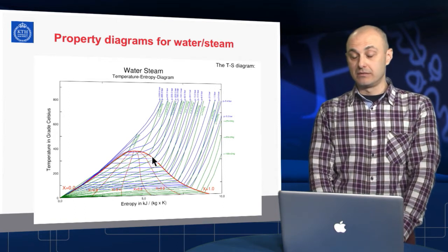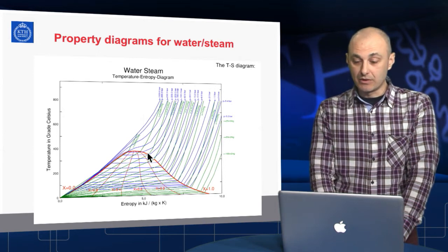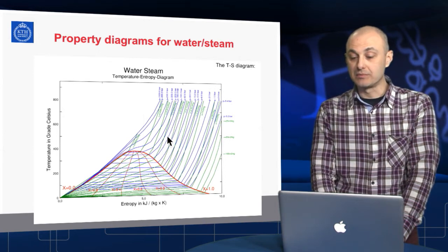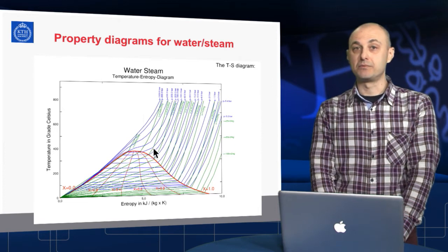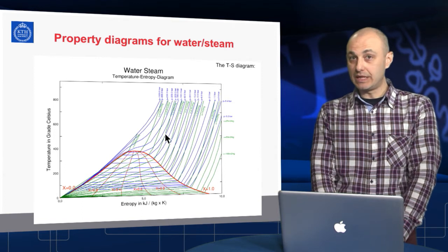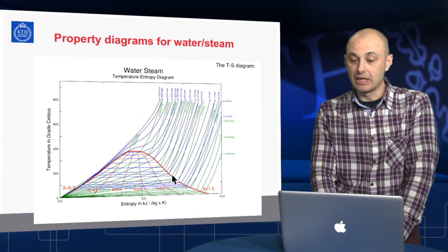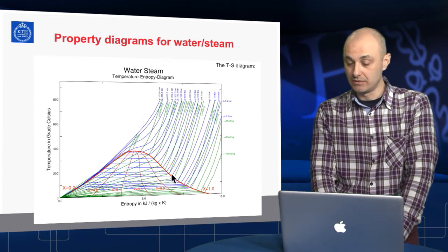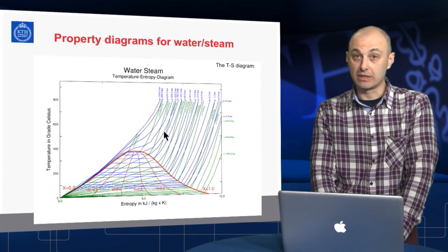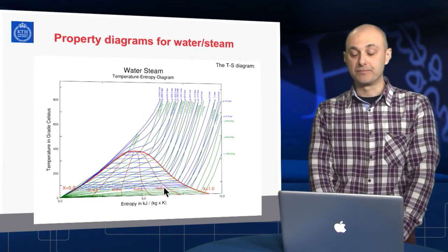The real power cycle in practice would be sliding along a constant pressure line as long as we perform the boiling process in the boiler. As soon as we let the working fluid expand, there would be a line straight down, in the ideal theoretical case vertically down, representing the expansion.